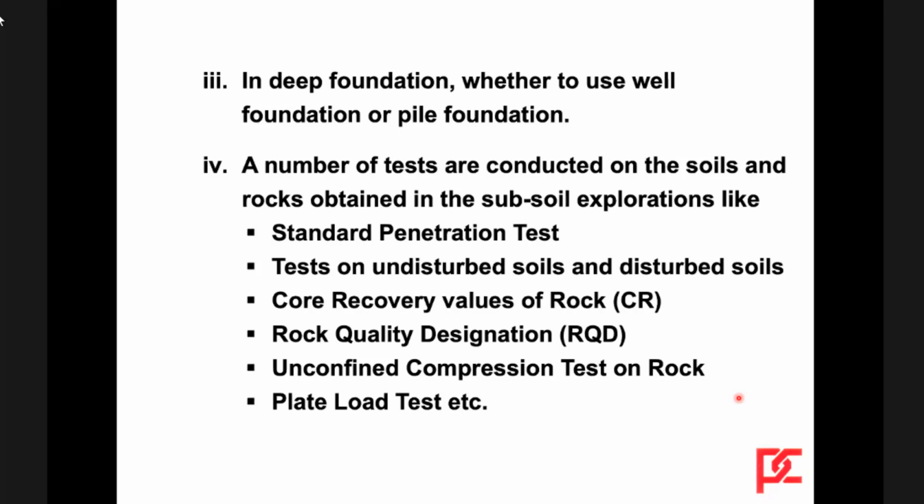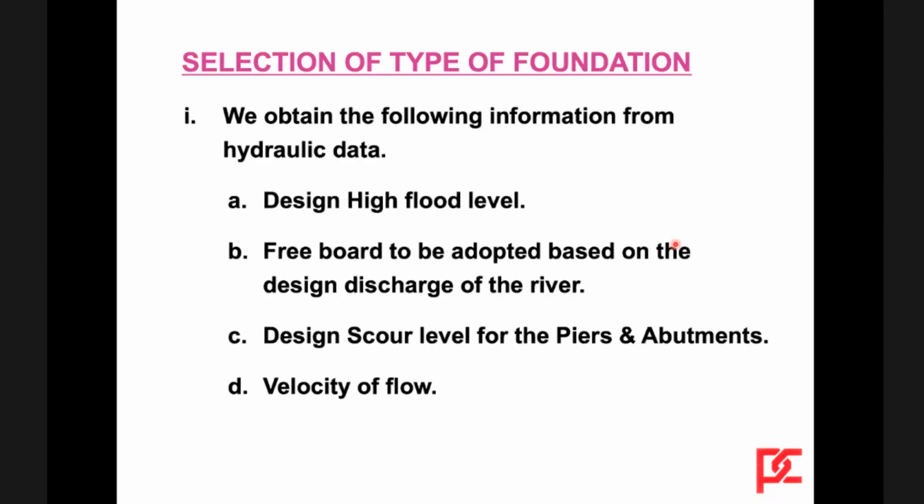A number of tests are conducted on the soils and rock in the subsoil exploration, like SPT test on undisturbed samples and disturbed soils, core recovery, RQD, UCS of rock, plate load test, etc. After getting all this information, it is used to select the type of foundation.